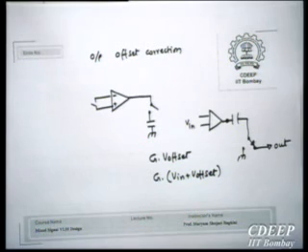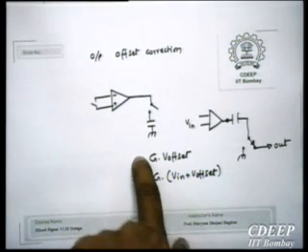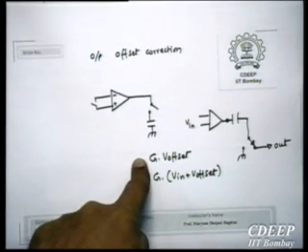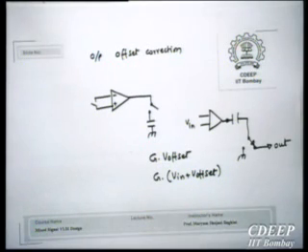Take the difference, it will correct the offset. That is true if the gain remains the same. That means you have a linear system, right? The gain remains linear over this range. So therefore, this will not work if you don't have sufficient headroom at the output of your op amp, right? And that requires that the product of G times offset should be reasonably small. And therefore, you must be operating this at a low gain. Okay?